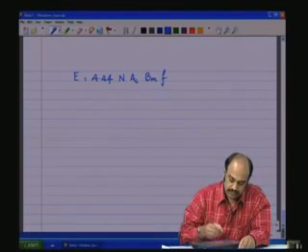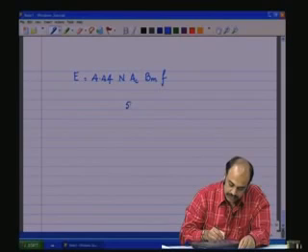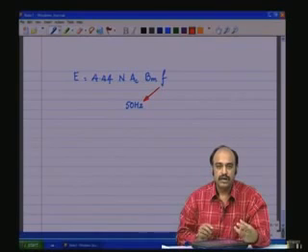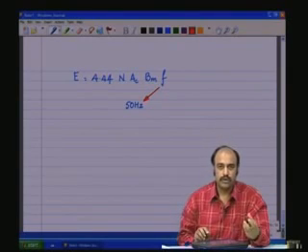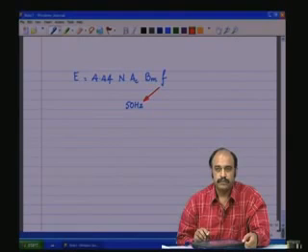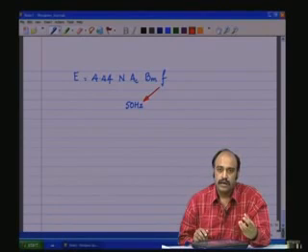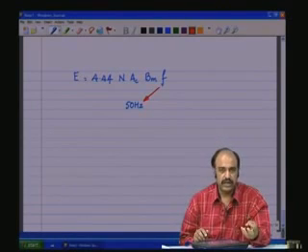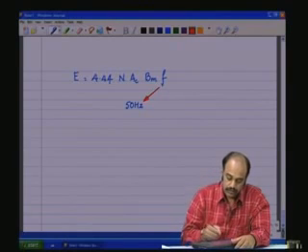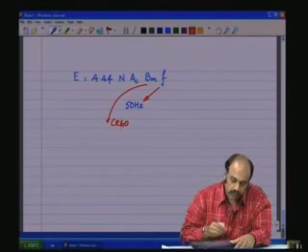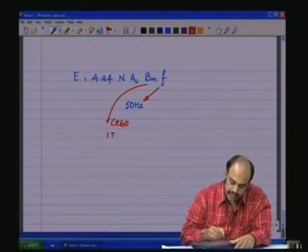Now, here for our mains, which is 50 hertz, the most common types of core materials in the market, especially for the 50 hertz frequency, are the CRGO, which is the cold rolled grain oriented, or the CRNGO, the cold rolled non grain oriented, which is slightly less expensive. So, if we are using, let us say, CRGO, this would be around 1 Tesla as the design value.